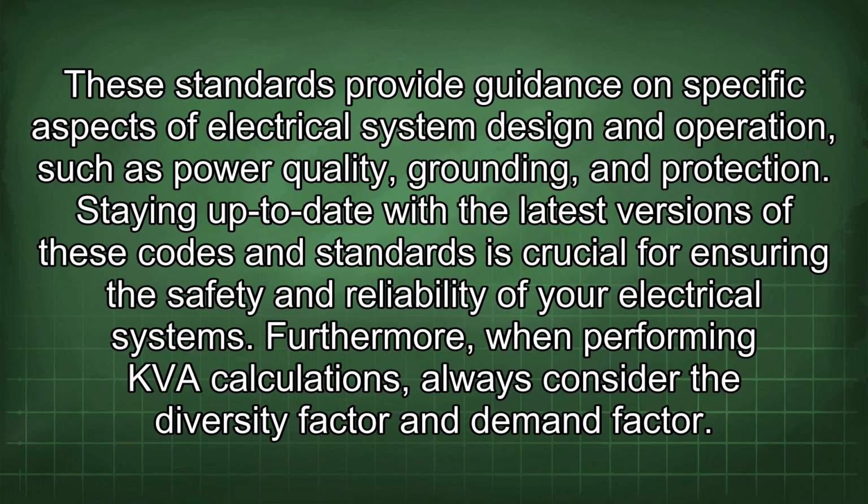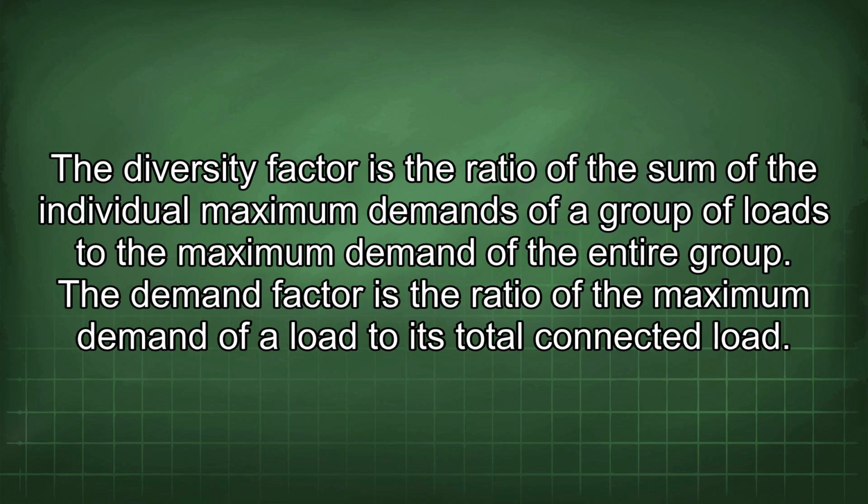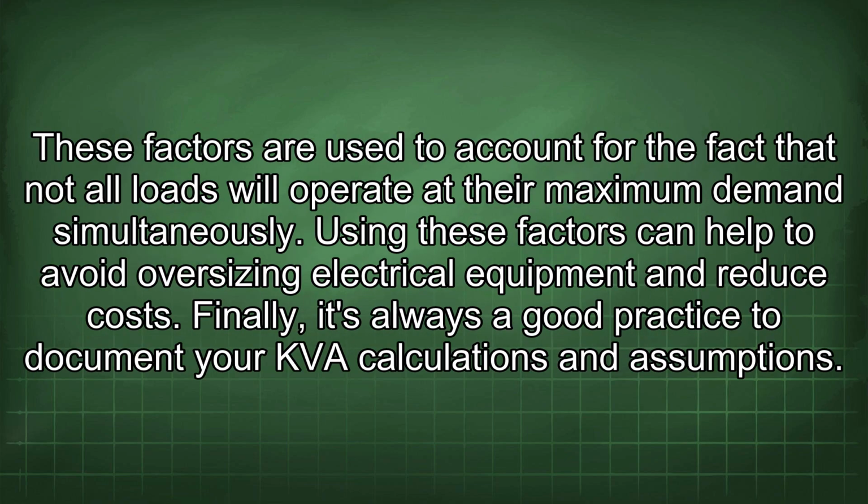Furthermore, when performing KVA calculations, always consider the diversity factor and demand factor. The diversity factor is the ratio of the sum of the individual maximum demands of a group of loads to the maximum demand of the entire group. The demand factor is the ratio of the maximum demand of a load to its total connected load. These factors are used to account for the fact that not all loads will operate at their maximum demand simultaneously. Using these factors can help to avoid oversizing electrical equipment and reduce costs.